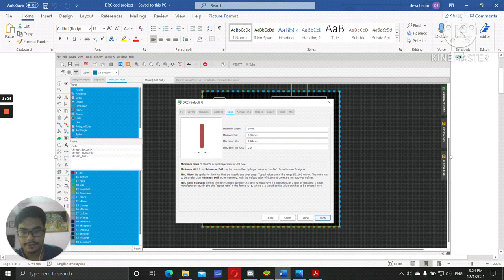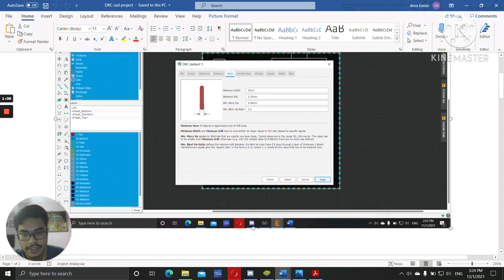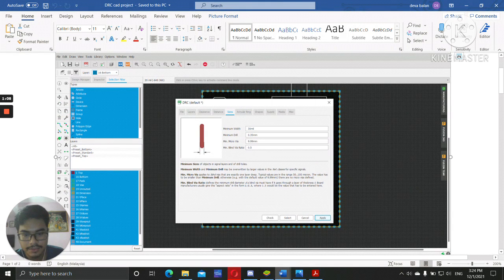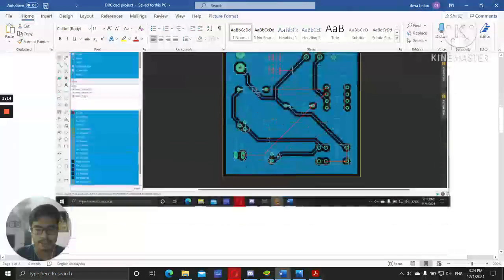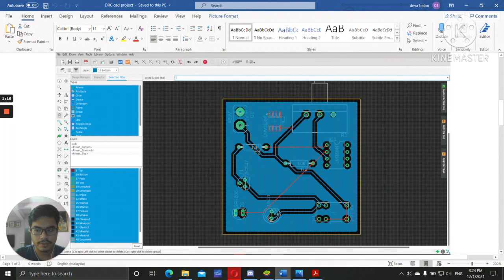For the design rule check, we checked the wire sizes by changing them from 10 mil to 30 mil. Then we applied it and we checked, and this is the final product of our layout. You can see the wire connections are perfect. The red ones are the ground connections, so they are perfect too. This is the perfect circuit of our PCB.